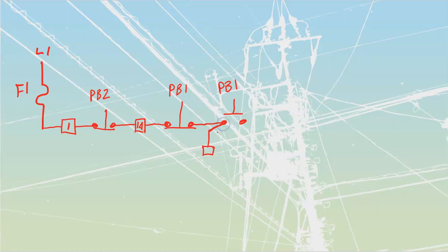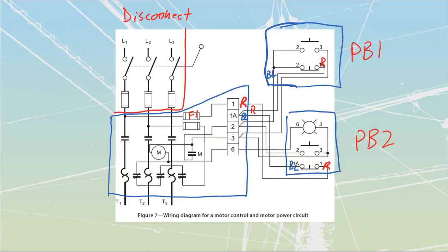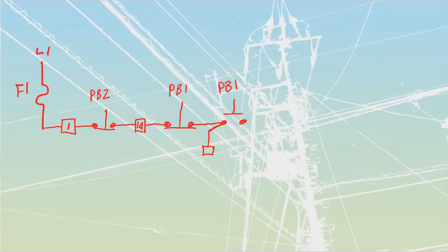This just indicates where it's making connections. So that if I was looking for this wire, I'd be able to say, it's coming off of the normally open one. Or if I drew to that one, I'd say it's coming off of the normally closed. If we look at this one inside of here, it's actually a splice, which we don't have inside of a proper control circuit. But that's what they've drawn this thing in here as.